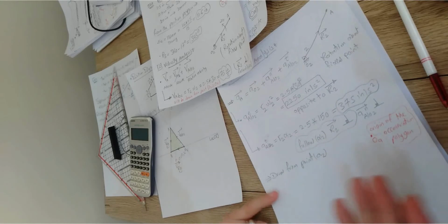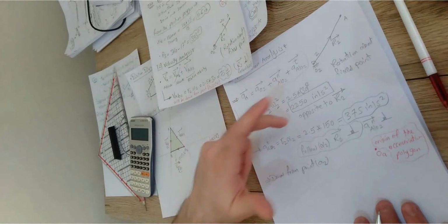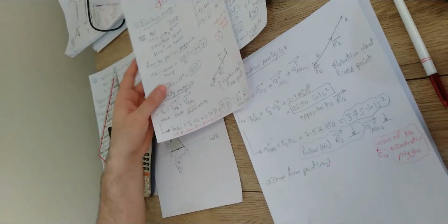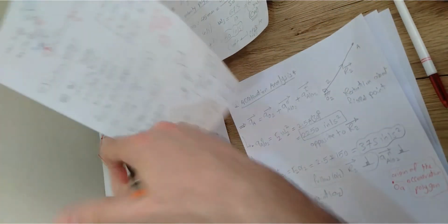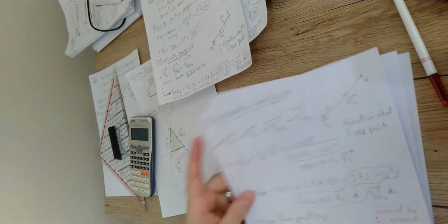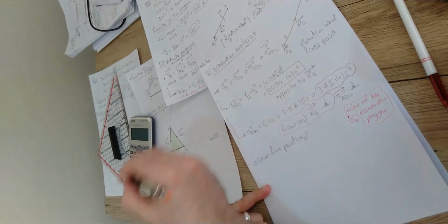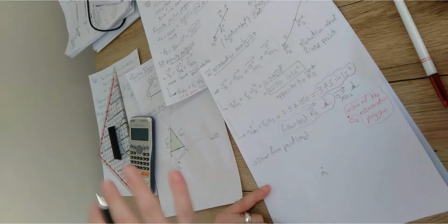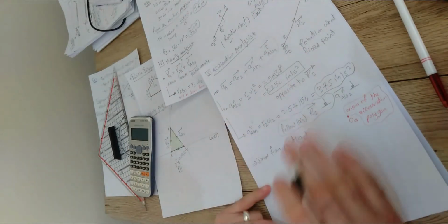So basically both are fully defined in terms of direction and magnitude, because the direction of alpha 2 is already going in the counterclockwise direction. So how can we draw these two components? In the velocity, we had only one component. Now we have two components. It's going to be clear when we draw. Assume that this is point O2. We agreed that point O2 will be considered as OA, so we are pretty sure that we have a location for O2.